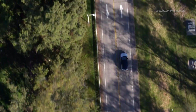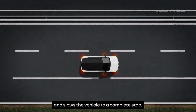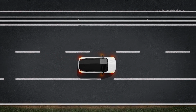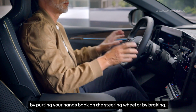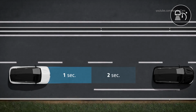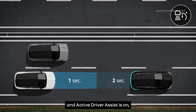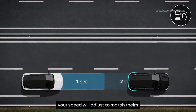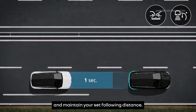If you don't respond, Active Driver Assist turns on the hazard warning lights and slows the vehicle to a complete stop. You can cancel this maneuver and the Active Driver Assist at any time by putting your hands back on the steering wheel or by braking. If you come up behind a slower vehicle in the same lane and Active Driver Assist is on, your speed will adjust to match theirs and maintain your set following distance.